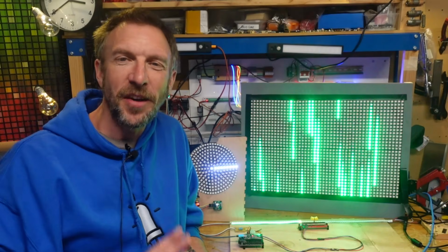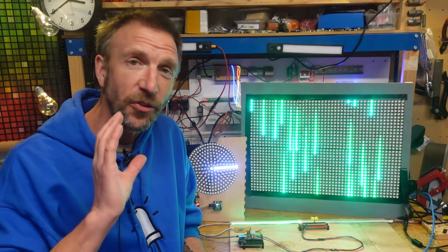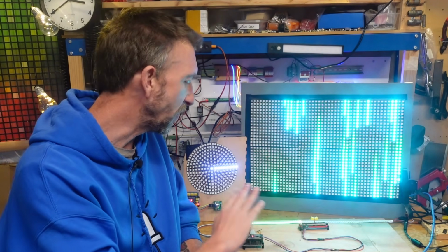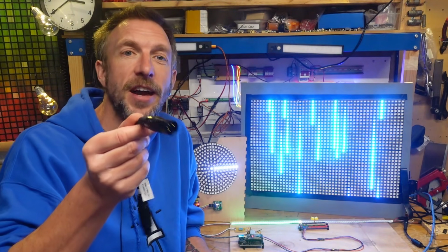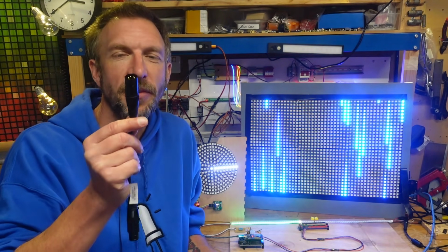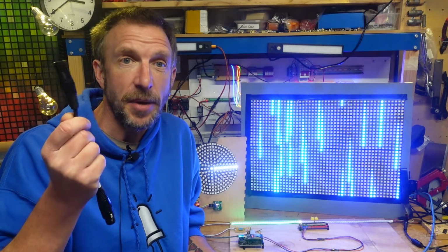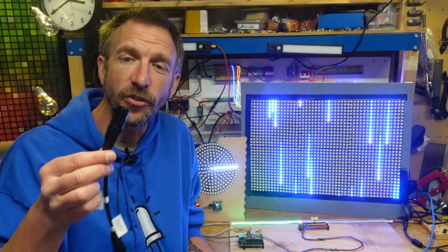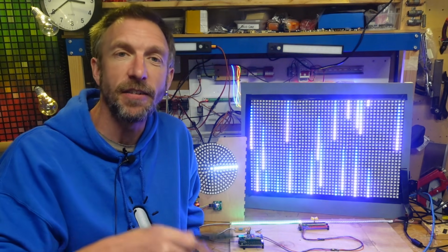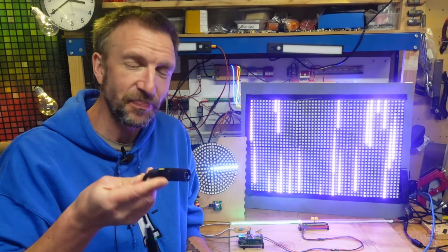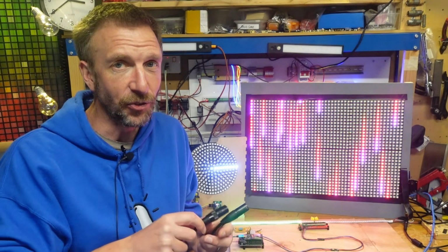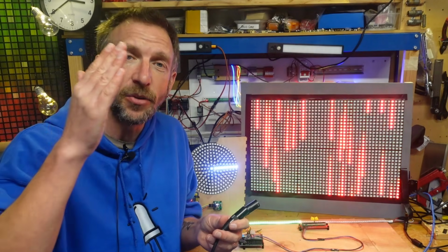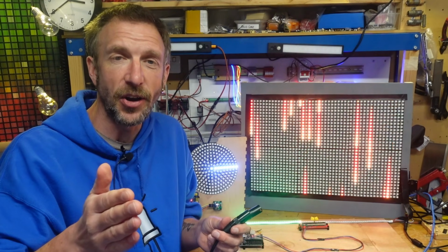So let me say some more about the sACN format, which I'm using to send data from the PC to the ESP32. Now, you may be familiar with DMX, which I've used a couple of times in my videos. Traditional DMX connects lighting fixtures together using one cable, which carries one universe of data. And a universe consists of 512 channels, each of which is a value somewhere between 0 and 255.